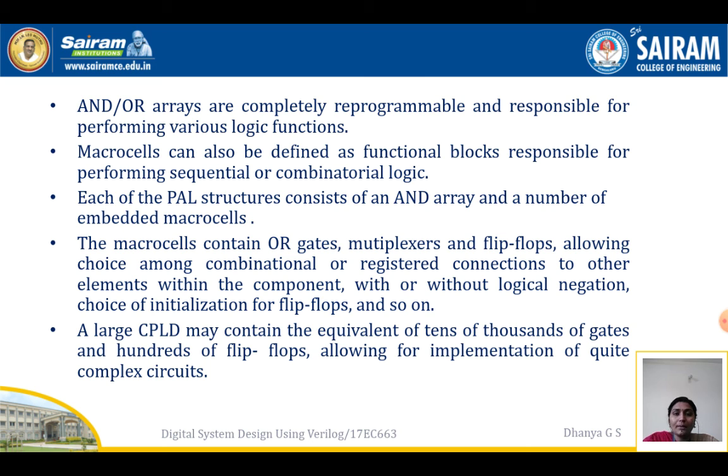AND-OR arrays are completely reprogrammable and responsible for performing various logic functions. Macro cells can also be defined as functional blocks responsible for performing sequential or combinational logic. Each of the PAL structures consists of an AND array and a number of embedded macro cells. The macro cells contain OR gates, multiplexers and flip-flops, allowing choice among combinational or registered connections to other elements within the component, with or without logical negation, choice of initialization for flip-flops and so on. So macro cells have so many functions.